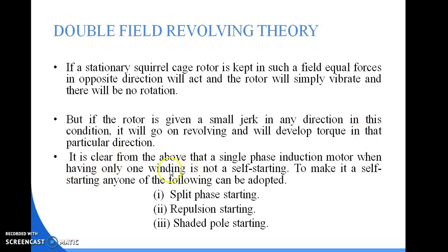It is clear from the above that a single phase induction motor, when having only one winding, is not self-starting. To make it self-starting, any one of the following can be adopted, and the methods are split phase starting, repulsion starting, and shaded pole starting.